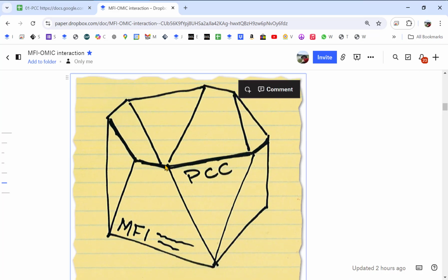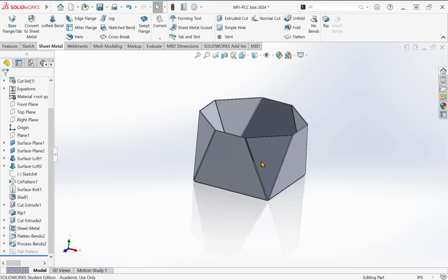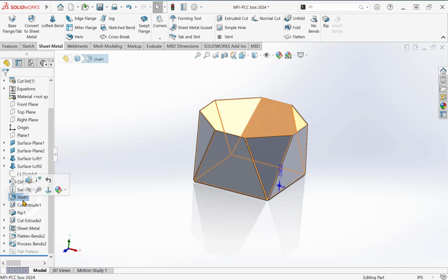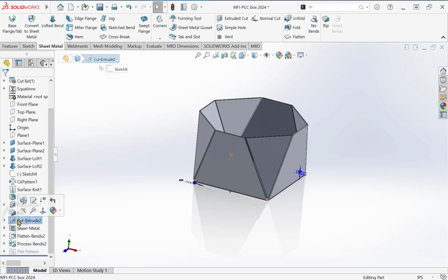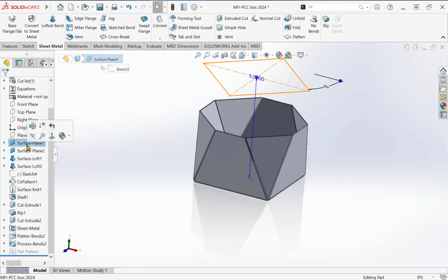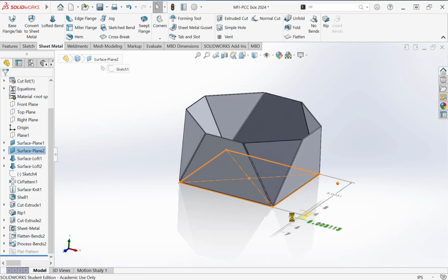I think the box should be slightly taller. So to me, this box is a little bit too short. So in SolidWorks, if I click on any bit of this model, as I click through the different features, SolidWorks will give me access to the dimensions that build those things. So each sketch will have the dimensions and these little blue handles. And as I drag the blue handles, I can actually change the model.